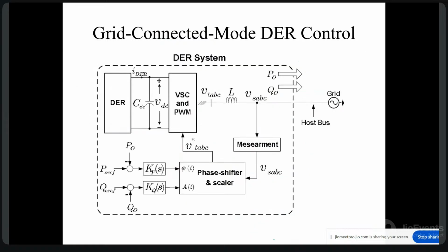So let us take the one operation that is grid connected mode operation. As we have discussed, the grid voltage and the frequency are fixed because it is a grid connected, non-autonomous mode. So we need to control only real and reactive powers, right? So based on the economic dispatch, or the optimal dispatch, or any other strategy, for example, I'm having a PV source, a renewable energy source, what amount of the power should I supply to the grid?